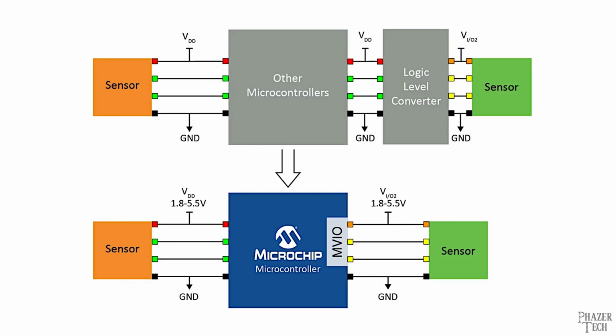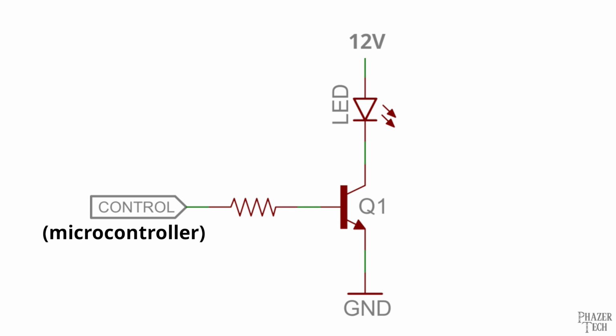In other words, these output pins are extremely low power and aren't meant to power devices, but rather they're just meant for communicating with sensors and other microcontrollers, or to activate larger external transistors, which will then be responsible for supplying the power to whatever device needs to be powered, such as lights, motors, relays, and countless other devices.